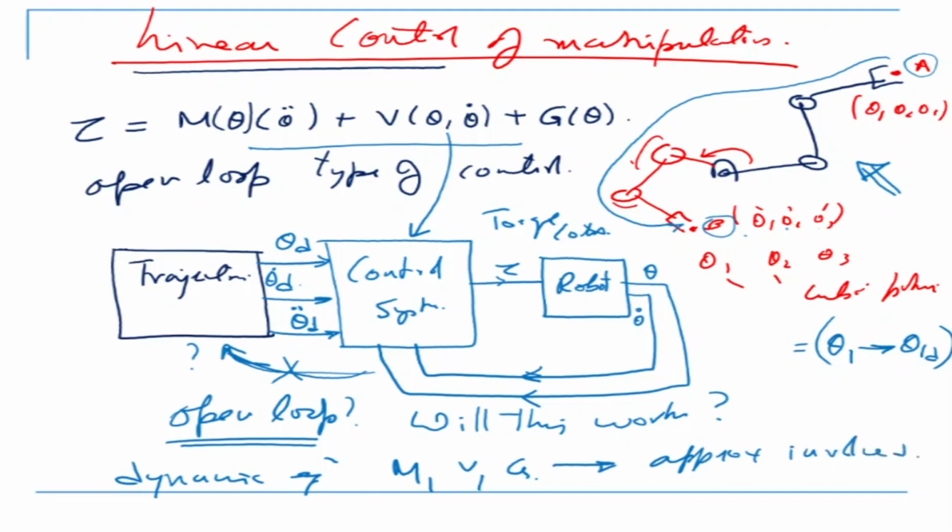What do you mean by that? When you look at a robot, for example, I have independent joint control. So I have a motor, I have a gear, I have an encoder. So the exact inertia matrix is not possible to obtain, because you may know the shape of the link, but in the link there will be screws, nuts, bolts, there is a motor which is fitted, there is a gearbox which is there. You will not know the exact inertia of those parameters. It's not possible to find. So it basically means that this would be approximate in some way.